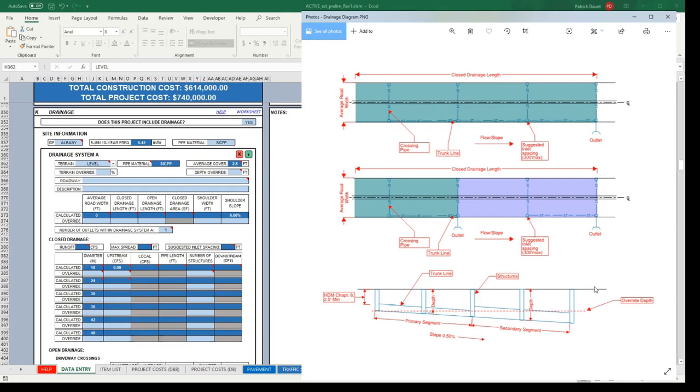This is just an assumption. Again, we have no ability to track undulations in terrain, high spots, low spots, or pipes bucking grade. There really isn't a way to capture that in this preliminary stage. So, in order to get a better quantity on excavation, I just assumed that the pipe was generally getting deeper as you increased in length at a rate of 0.5%.